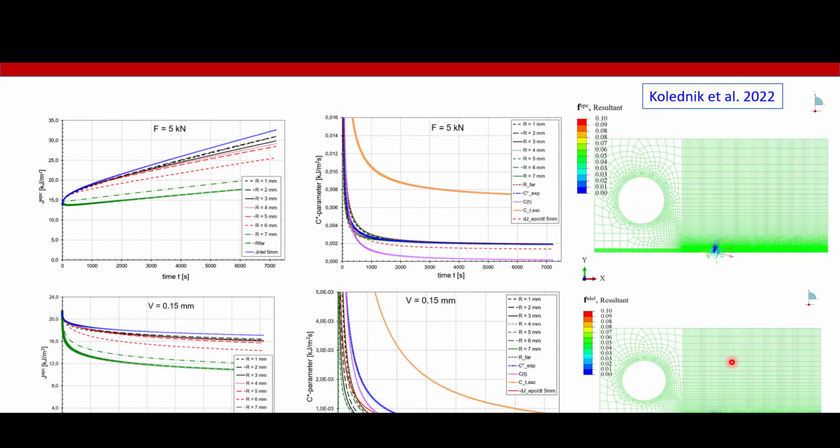So with this information, you can also look at these two plots of elastic plastic creep configurational forces and non-linear elastic configurational forces. And you see that non-linear configurational forces are looking a little bit higher. These two images are taken at the same value of time for a static crack. And why do we call it elastic plastic creep? Because here the total energy includes elastic energy, plastic energy, and creep strain energy. So when you only take elastic energy, we call it FEPC. And when we take all the strain energy densities, then we call it nonlinear elastic, because then it behaves like a nonlinear elastic theoretically.